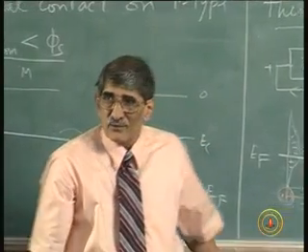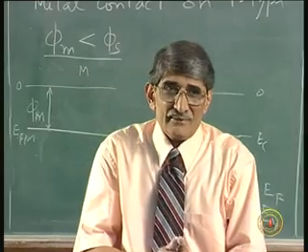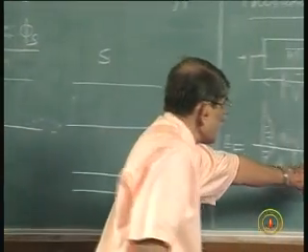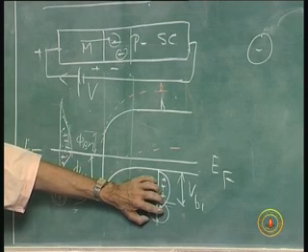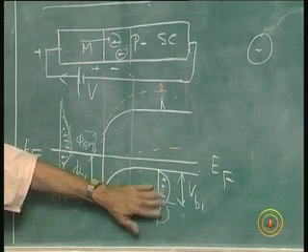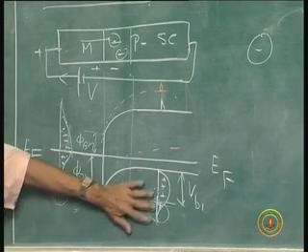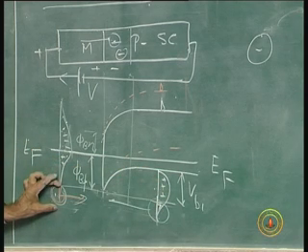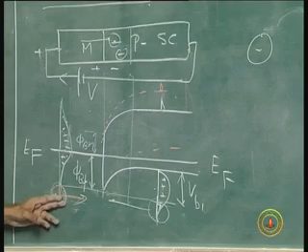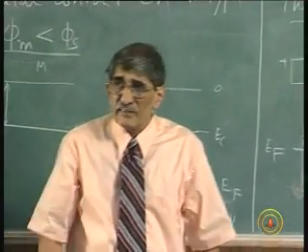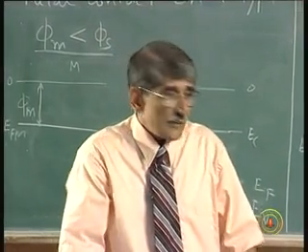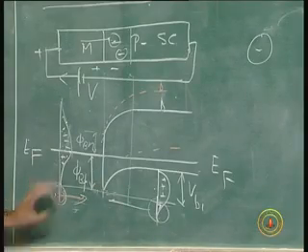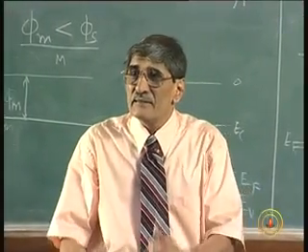So, here again, this will be forward bias or reverse bias. Reverse bias, you are blocking, you are not letting these holes cross, you are discouraging them from opposing the current flow here. So, you are removing them out of competition with these holes. Once this is removed out of competition, only this is there and that is constant. If we keep on increasing the reverse voltage, this goes on increasing, and at the end you will have I naught, which is decided again by phi Bn.